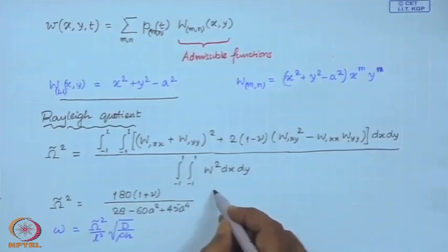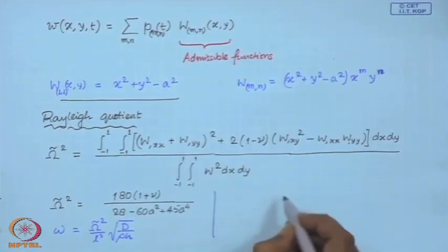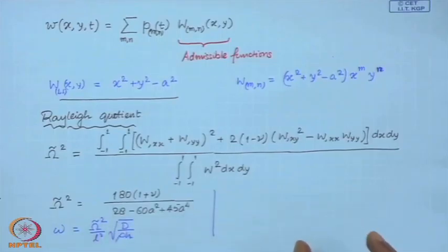Now, if you want to improve the support, suppose you ask the question: what should be a good radius for this circular support, so that the plate is well supported? In that case, what we are asking is what radius will give a very high natural frequency. High natural frequency would mean the support is quite stiff. So, what would result in a very high natural frequency?